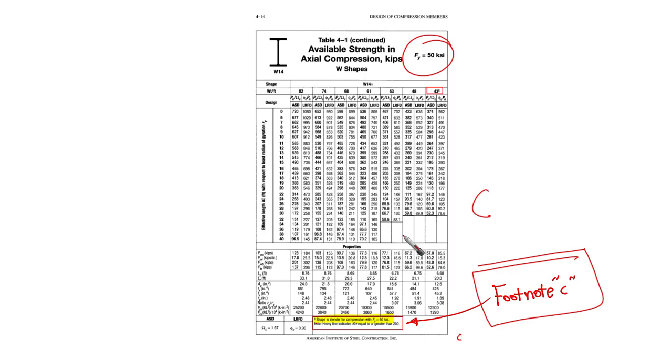This means that, like we are talking about table 4-1 here, the available strength is already computed based on taking into consideration the slenderness effect.